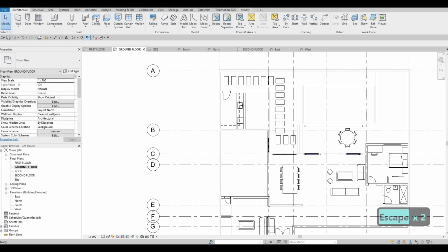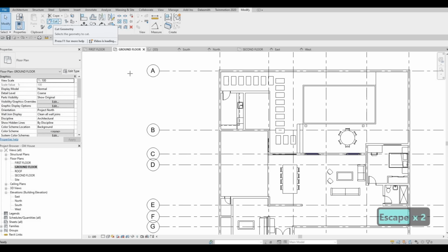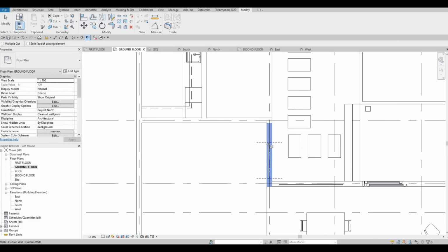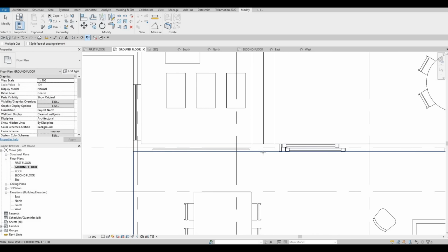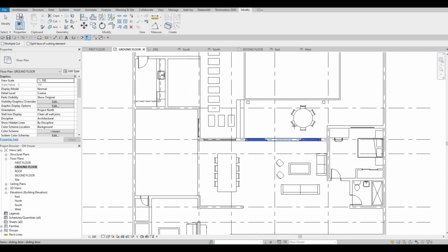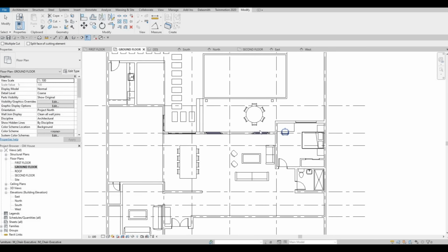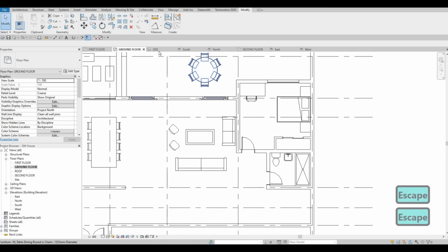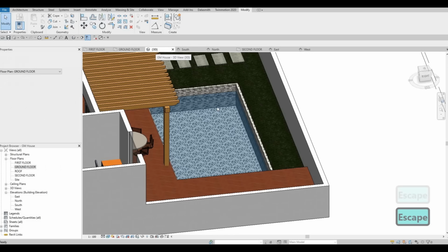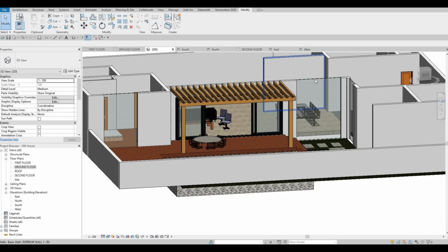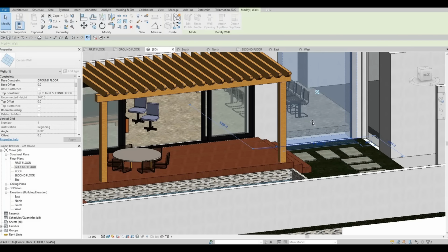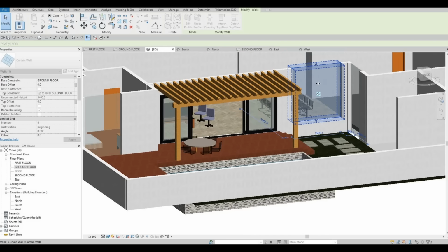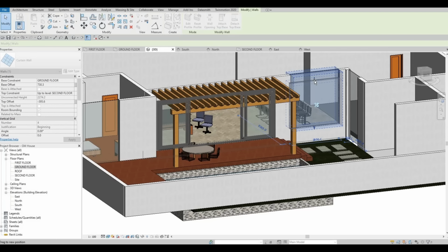And then in order for us to cut that, we need to cut geometry in order to show those. So here I'm gonna select the wall first, then the curtain wall. There we go. And we want to show how it looks. I don't want it to be all the way below there, so we could just pull it up like that and then pull this one down.